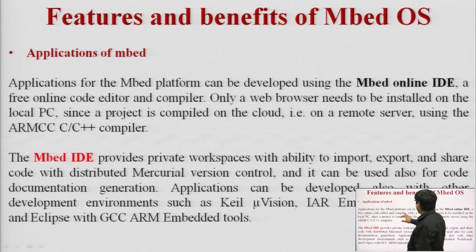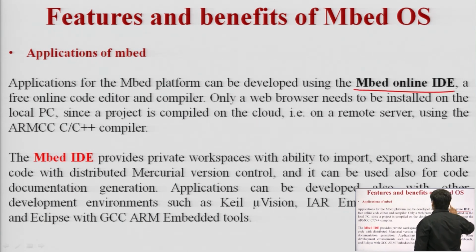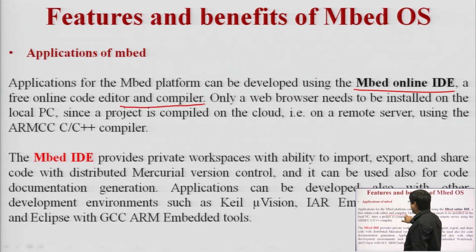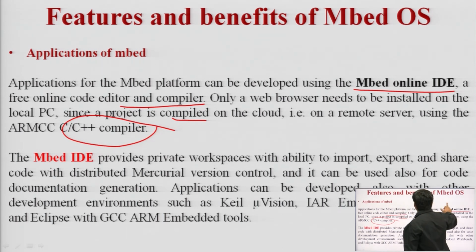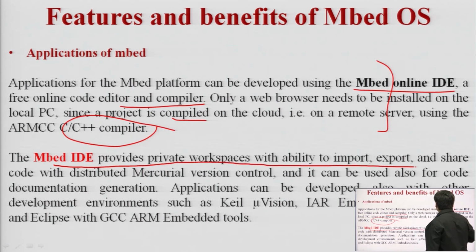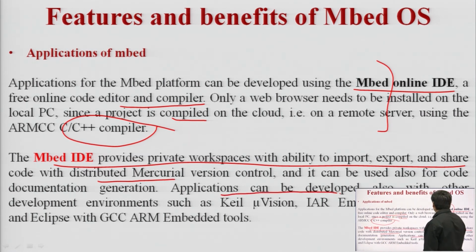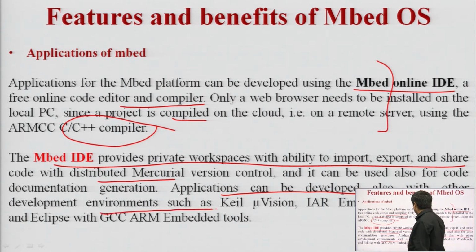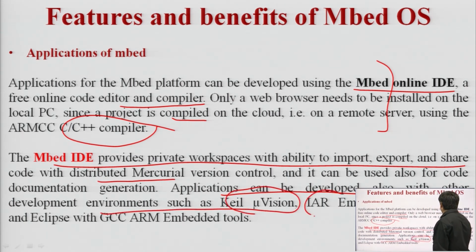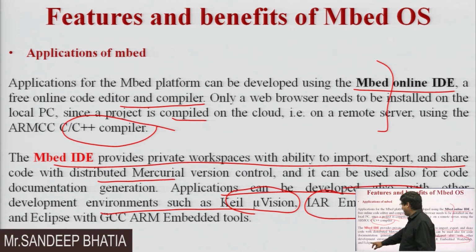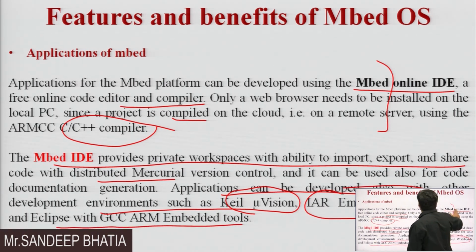Applications in embed can be developed by using the online IDE. It has its own compiler, collaboration, and a large number of tools. It is compatible with the C++ compiler. A large number of ports are available, you can use them in your system. The embed IDE provides private workspaces with the ability to import, export and share code with everyone. Anyone can export a library, anyone can import the libraries. Applications can also be developed with other development environments such as Keil Microvision, IAR Embedded Workbench, which are compatible, and Eclipse with GCC ARM embedded tools. So, a large number of applications are available.